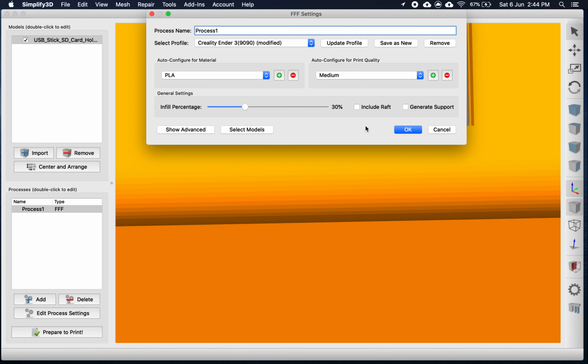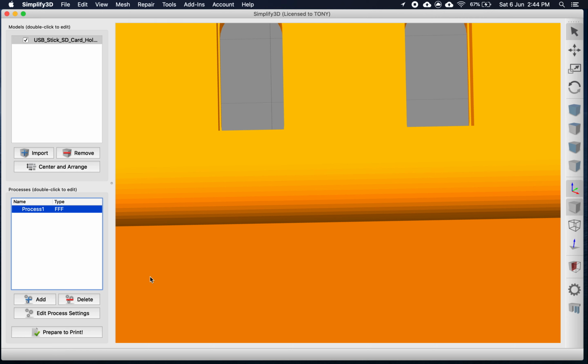Please don't use more than 80%, because it will be over extrusion, so it might damage the machine as well. The machine tries to squeeze in more material, but the part is not allowed to absorb it. What we realize is our software and the machine are not fully calibrated on infill. So maximum 80%. Don't use more than 80%.